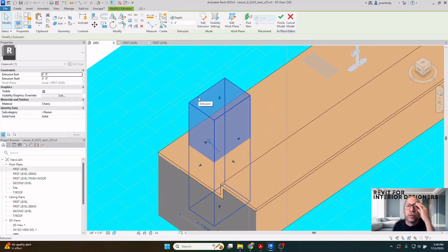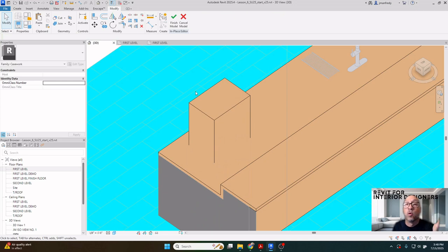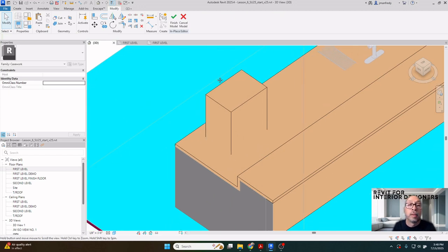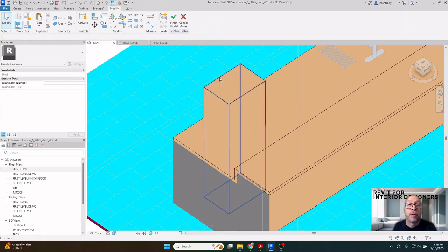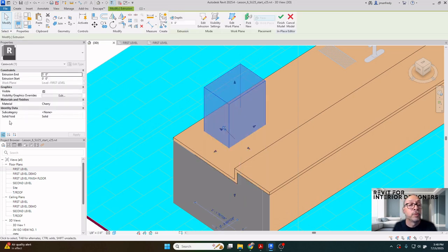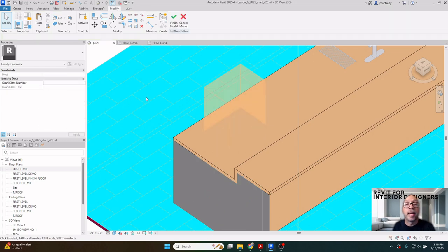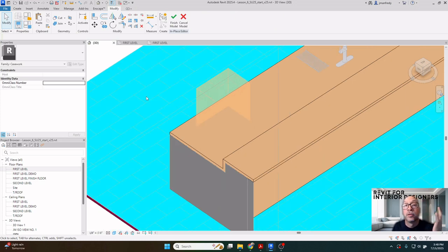Normally this would be invisible, sort of semi-transparent when it's set up to be a void. A void wants to carve itself out of a 3D model. If it's not a void, you can take this and turn it into a void. And when I click on this over on properties, under here's a solid void, it's a solid now. I can make it into a void here. So it'll act like I went to the void object from the beginning. Just another method of doing the same work.